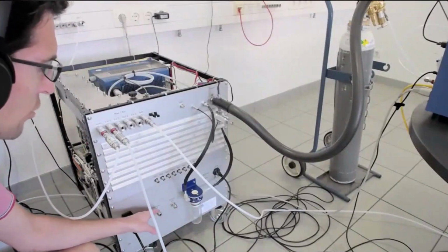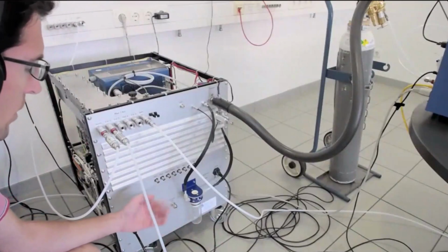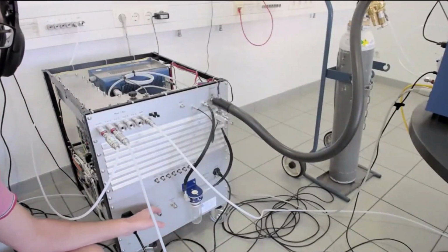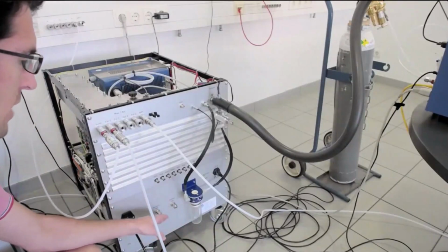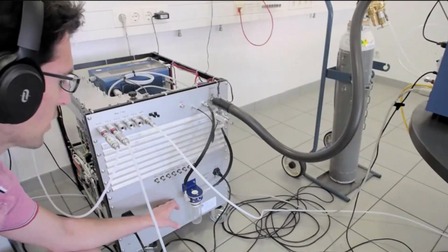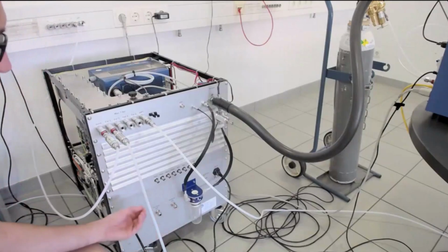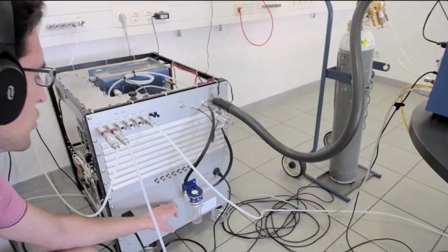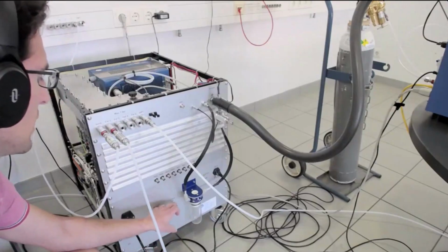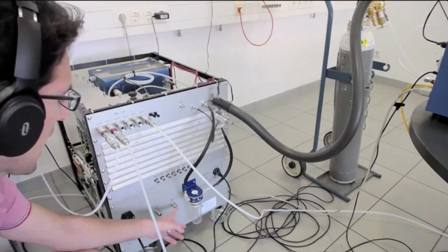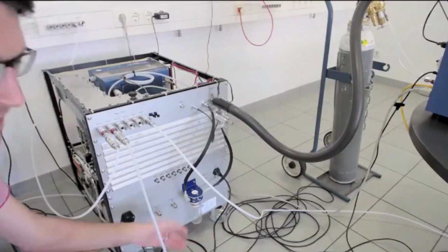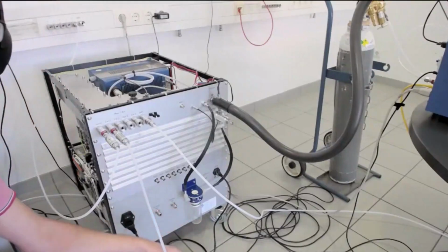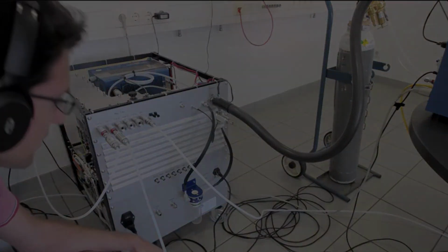So the vacuum out outlet is the one which comes from the high vacuum chamber, going to the turbo pump, pre-vacuum pump, and then coming out here. And the sample out port is the one which draws the gas from the engine exhaust system and has to be vented, of course, so not into the room, but you have to attach a line here and feed it into a venting system in order to not get excess CO2, which is usually present in an engine, into the ambient.